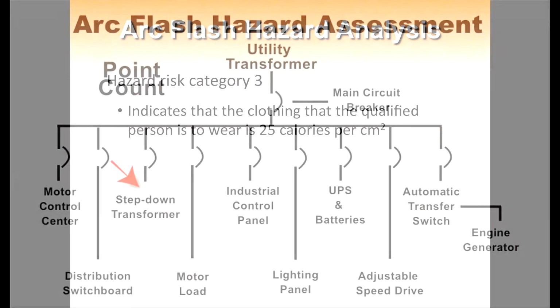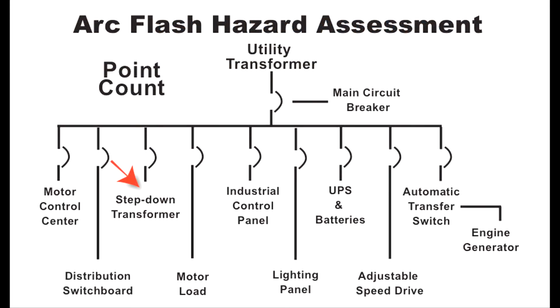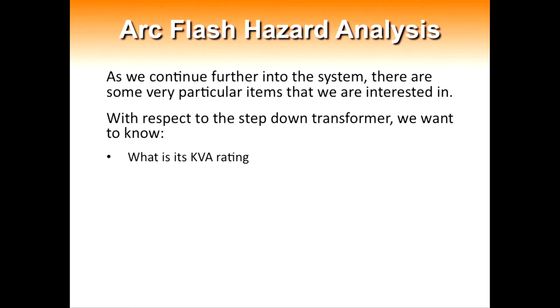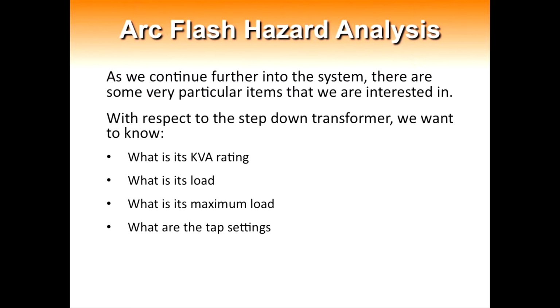As we continue further into the system, there are some very particular items we are interested in. With respect to the step-down transformer, we want to know its kVA rating, what is its load, what is its maximum load, what are the tap settings, what is the impedance, how is it cooled.